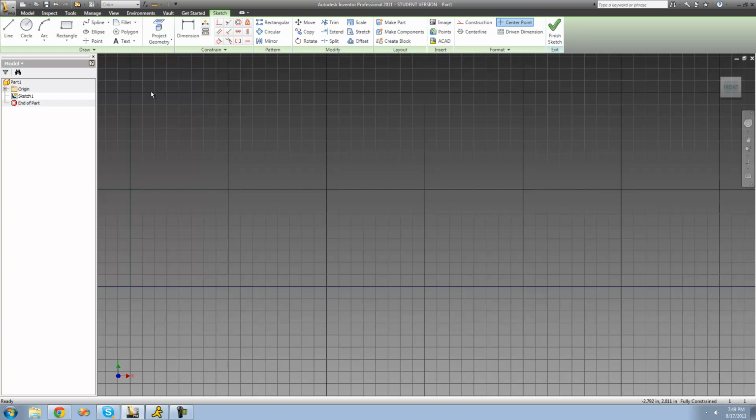And that's pretty much all there is to having text on your sketch plane. But there's actually one other way to have text. So that's called the geometry text. And basically that's just used if you want to wrap text around something, like if you want your text to be on a specific line or around a circle or something like that, you can use that tool. So let's say we just want to have our text wrapped around this circle right here. Let's draw a nice circle.